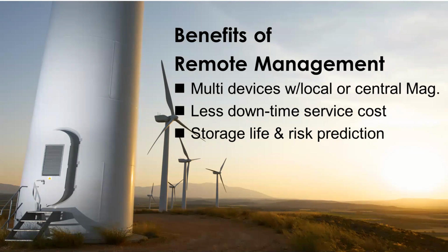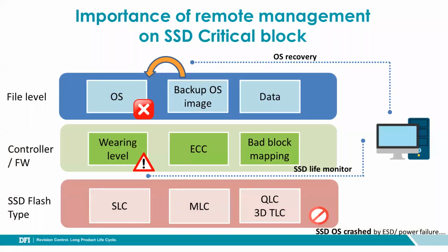And it's more important to monitor and predict the health status of storage now. Why? Due to the popular type of NAND flash keeps changing. The write-erase cycles change from 100K of SLC and 10K of MLC to only 1K of the currently popular QLC type.